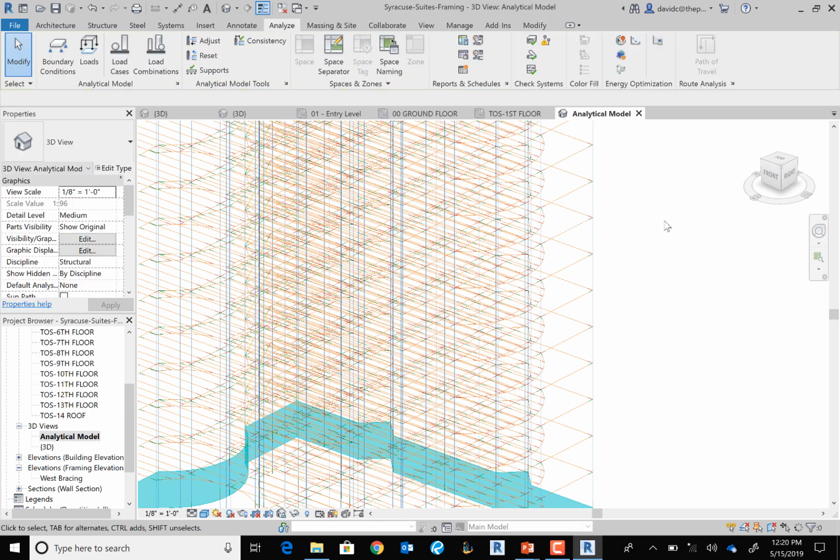Now, I also want to specify that this is not just the structural steel type of stuff. You're placing concrete walls, that is a structural element, floors, structural elements, anything like that, okay? And let's say you've placed, I want to say modify sub-elements for your flooring, right? If you're placing drain points or anything like that, the thickness of your floor is changing, it's going to take all of that into account with the analytical portion of that floor.